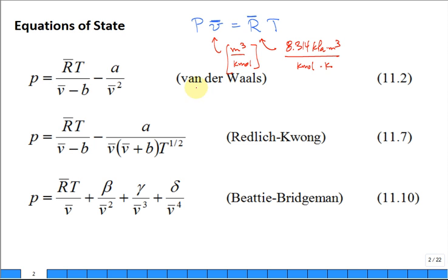That's the universal gas constant. Here's another equation of state, an EOS. Sometimes you'll see that EOS, the Van der Waals equation. Well, we understand R bar and V bar. There's a V bar squared. What do they have? They have constants that help fit. So the value of A and B depend on this fluid or this substance. Redlich-Kwong equation of state. Another constant.